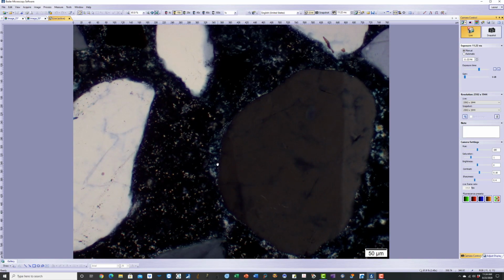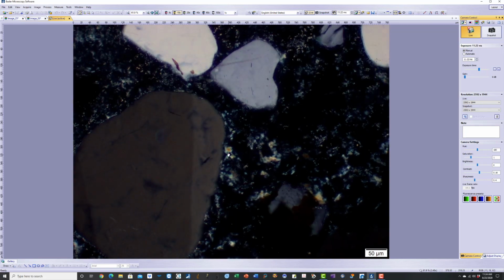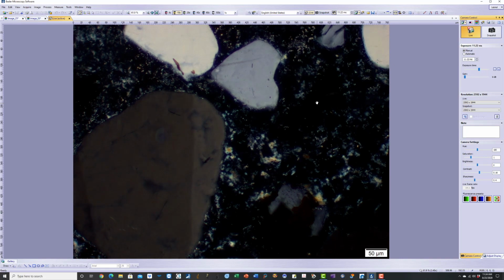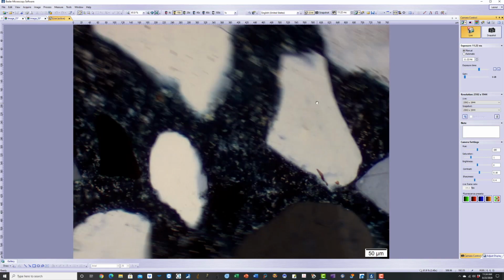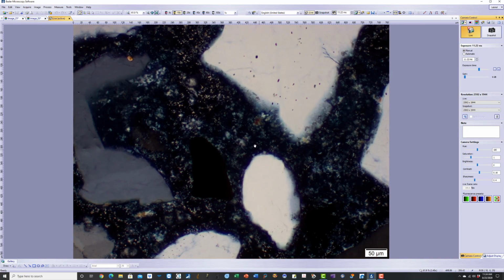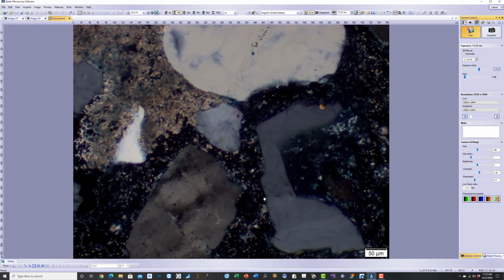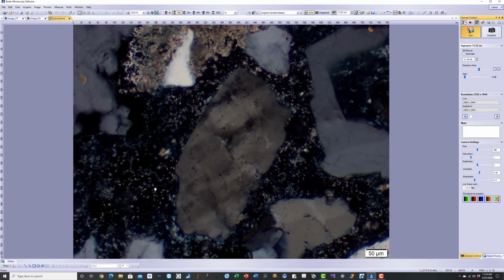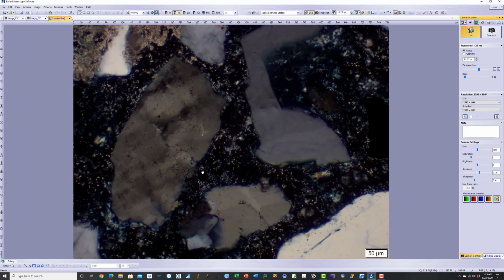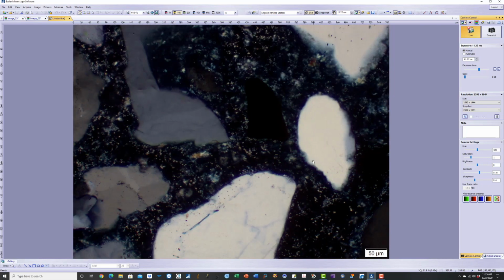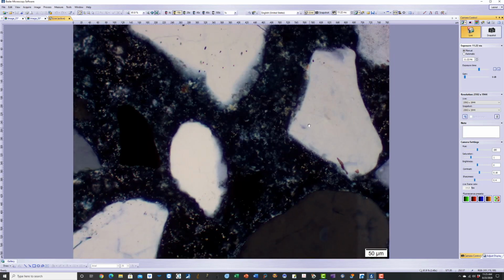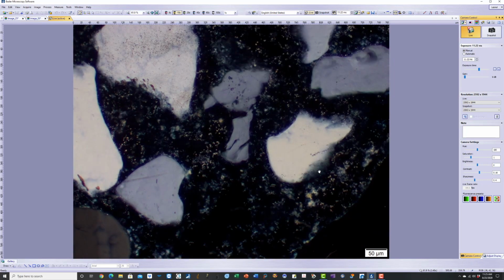The primary calcium hydroxide crystals, and most of these calcium hydroxide crystals have been dissolved by the migrating moisture to create the efflorescence. So the top portion of the mortar, you see very porous paste, and this porous paste is the result of leaching of the calcium hydroxide from the paste, leaching of this lime. So this skeleton, what you see here, is a non-carbonated but porous leached skeleton of the paste, where the lime portion